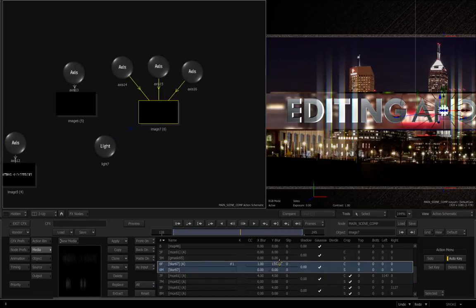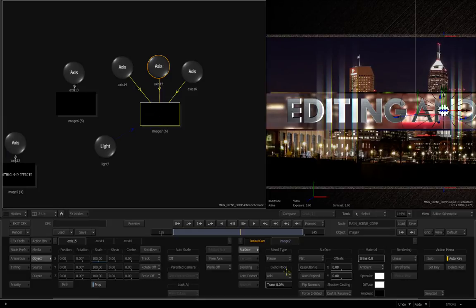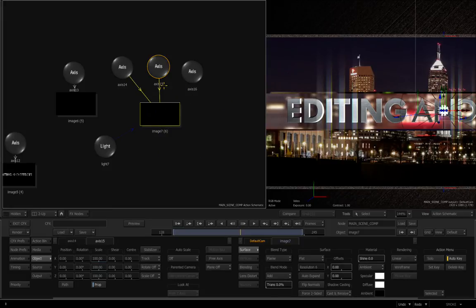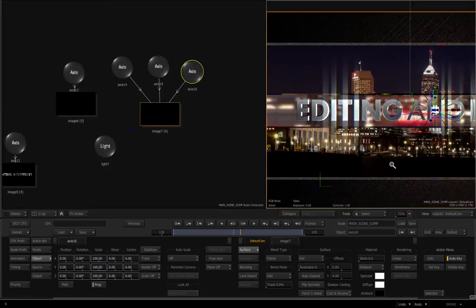There's quite a bit of blur in the Y value for these. Now, these 3 axis nodes are here, and as they connect, they basically duplicate and double and triple up this one image. If we look at the blend mode for it, you can see that it too is in add mode. But if I disconnect these axis effects, you can see that the initial one isn't very bright, even in add mode. So by simply adding another axis and connecting it, this image actually gets duplicated so that it appears more than one time. By adding a third, I'm now adding 3 layers because I needed this certain amount of brightness. So there's no need for me to actually duplicate this one image. I can just duplicate axes and connect it to it, creating basically an instance of this one image. So we look back through our effect.